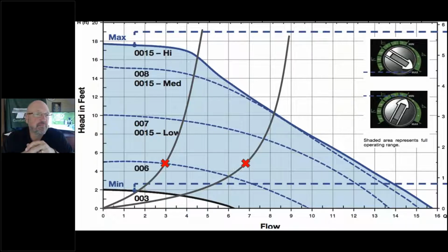That's a great way to run a zone pump system, because now you can dial it in to be exactly the speed that you need under design conditions. It's going to keep going at that speed as it gets warmer out, so it will be over pumping. That's one of the benefits of the Delta P or the Delta T VT2218 circulator, because it will change its speed not only based on zone valves opening and closing, but as a zone pump, it'll change its speed based on how cold it is outside to try to maintain that Delta T.